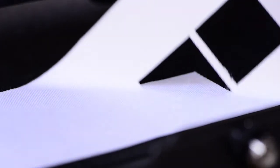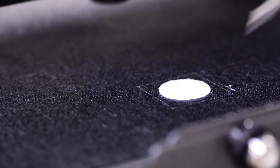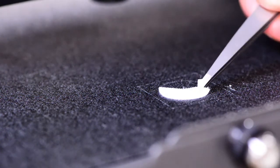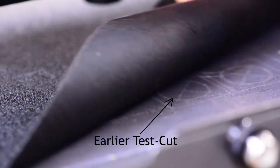So upon trying to weed it the first time, it doesn't look like I've got enough blade sticking out, because it didn't cut all the way through. So we'll adjust the blade a little bit more, and it's just the cap on the blade holder. Then I redo my test cut, and as you can see, it looks pretty good. It's already come out by itself, and each pie piece comes off one at a time without sticking to each other, and you can see the impression of that cut in the background twill. And even by lifting the twill up, you can see that it didn't cut all the way through. So that's a good test cut, and that means we're set.